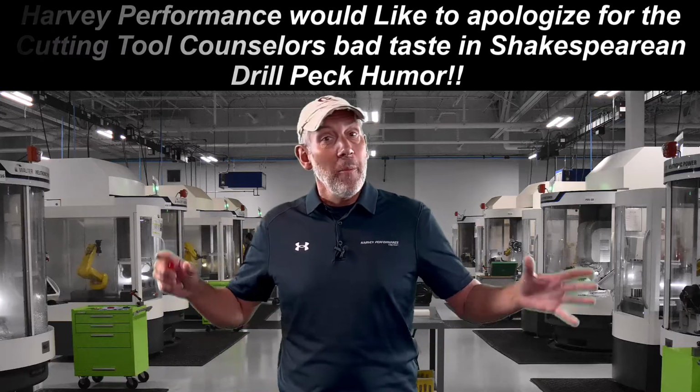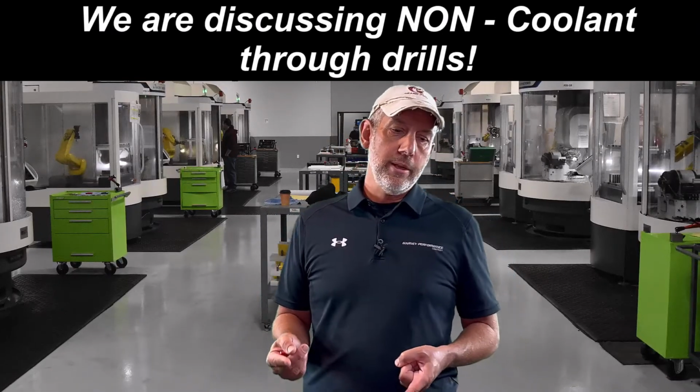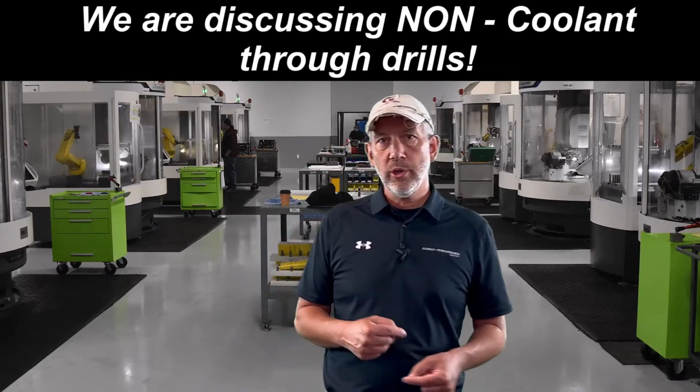But it's a great question. Should you peck? Should you not peck? Well, let's just start out right away by saying a deep hole is usually anything that's over 4 times the diameter on the drill. So deep hole is where you're going to start looking at pecking.